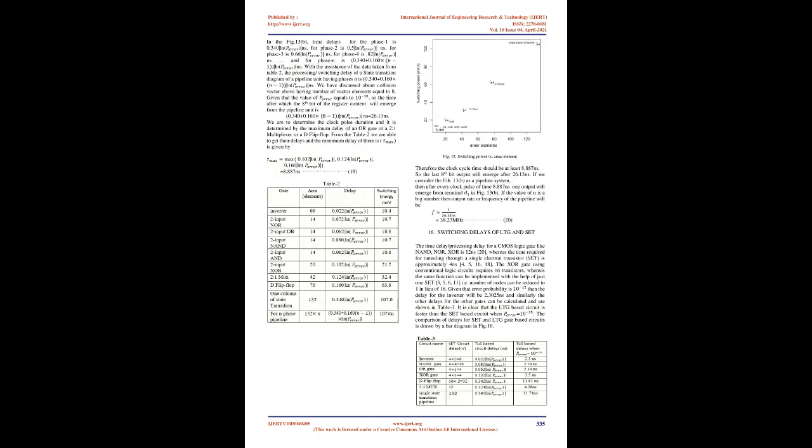It is considered that the probability of error equals 10^-12. We obtain a gate delay equal to 0.07281 ln(1/ε) ns, which equals 1.675 ns. In the same manner, we are capable of calculating the circuit delays written in Table 2.